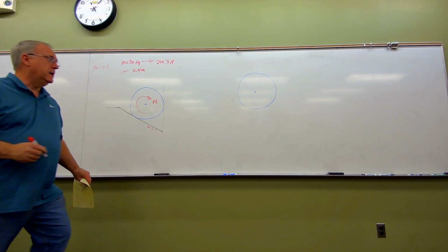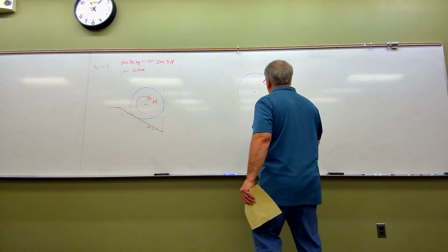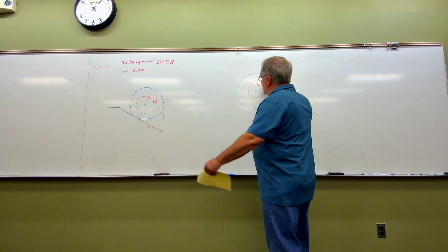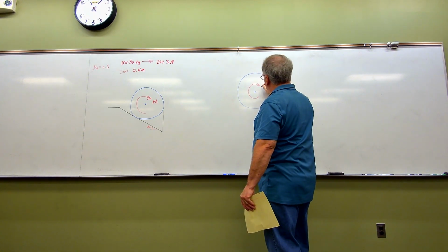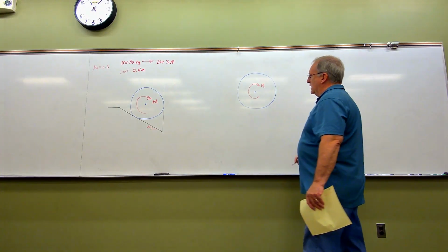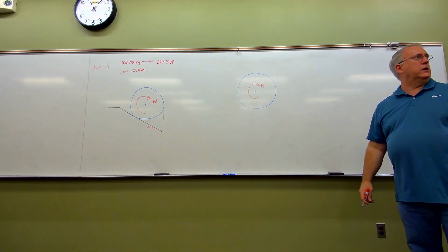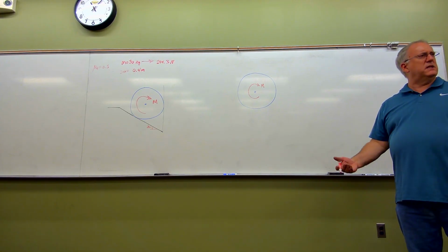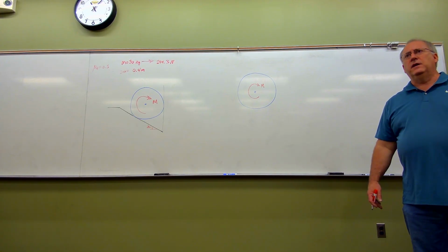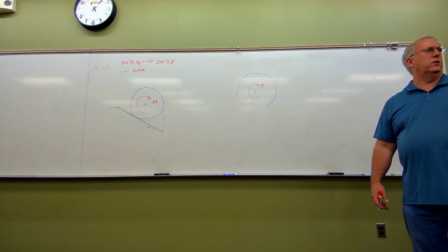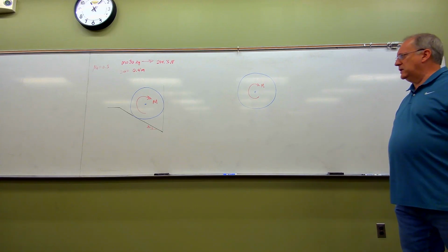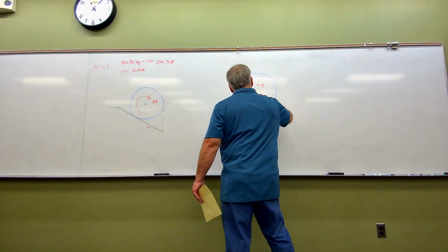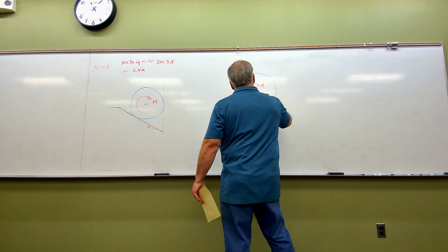Okay, folks, I'm not sure where you're at in your process of doing it, but let's do some of the things that we know. We know there's going to be this applied moment on there, and it was showed in the original diagram as a clockwise moment, so let's show it again as a clockwise moment there. We also know that this cylinder weighs 294.3 newtons, and because it's homogeneous, then we know that the centroid of the cylinder, as it would be with any circle, is right in its geometric center. So therefore, right down the middle here, I'm going to have this weight force of 294.3.